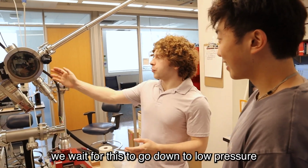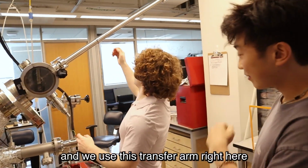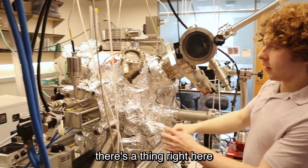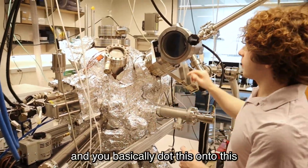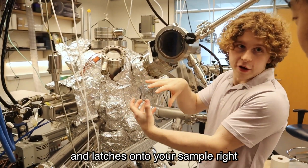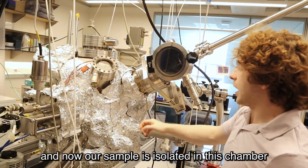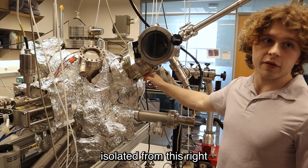So what we do is we wait for this to go down to low pressure, and then we open this gate valve, and we use this transfer arm right here to bring our sample down into this chamber. When we bring the sample down, there's a locking mechanism that goes all the way into the chamber, and you basically dock this onto this. There's an arm that comes out and latches onto your sample, right? And so then we transfer this sample into here, bring this arm back up and close this gate valve, and now our sample is isolated in this chamber, so it's isolated from this, right?